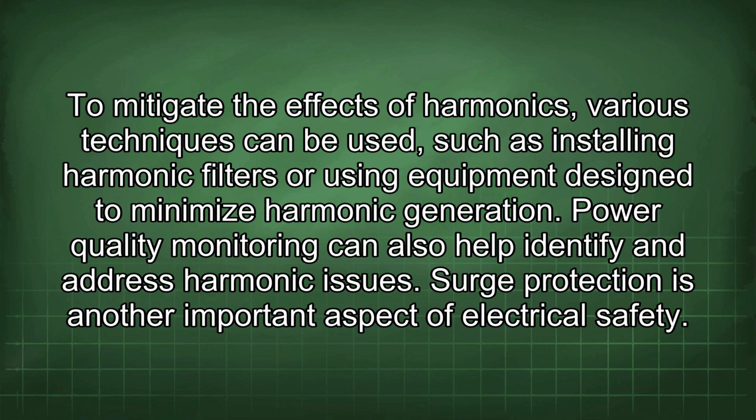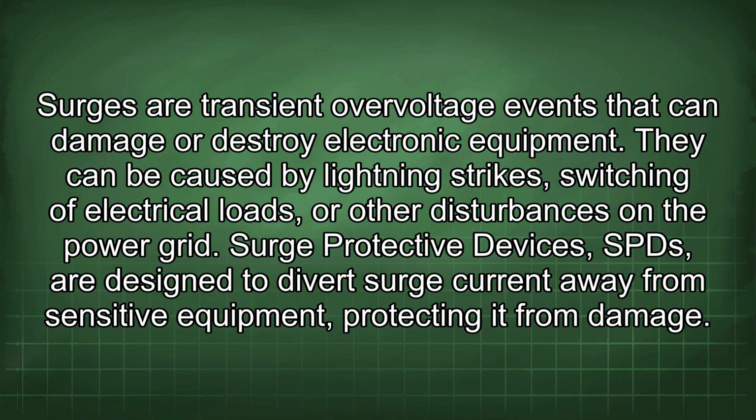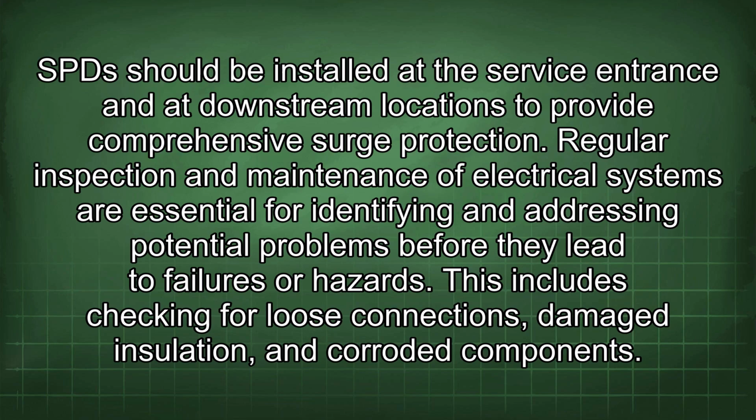Surge protection is another important aspect of electrical safety. Surges are transient overvoltage events that can damage or destroy electronic equipment. They can be caused by lightning strikes, switching of electrical loads, or other disturbances on the power grid. Surge protective devices, SPDs, are designed to divert surge current away from sensitive equipment, protecting it from damage. SPDs should be installed at the service entrance and at downstream locations to provide comprehensive surge protection.